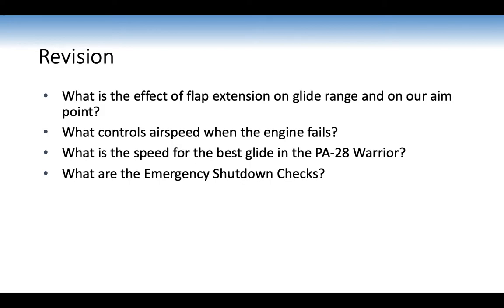What are the emergency shutdown checks? It's FMMM: fuel off, mixture, mags, master, switches all off. Important because in this lesson we'll be doing touch checks as well, and you'll shut down the engine also if you had a fire.